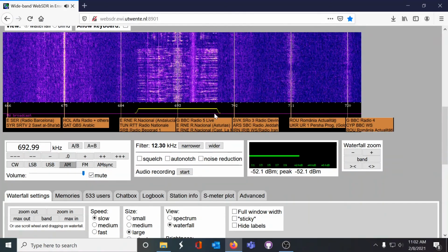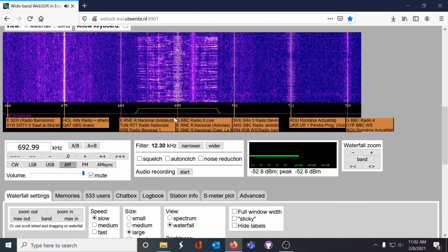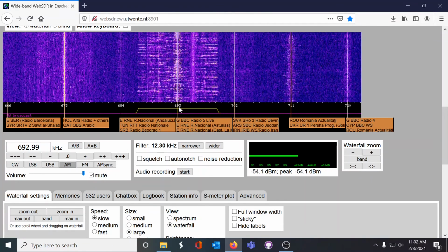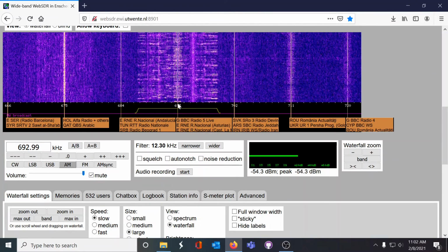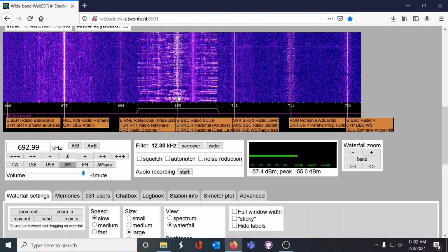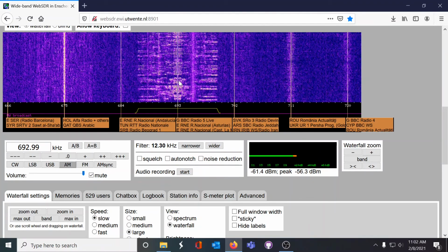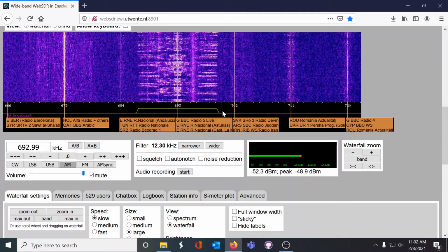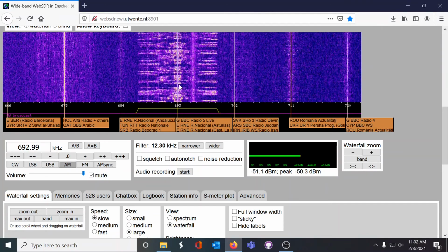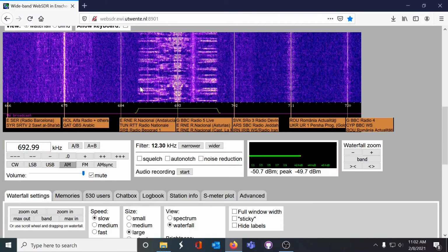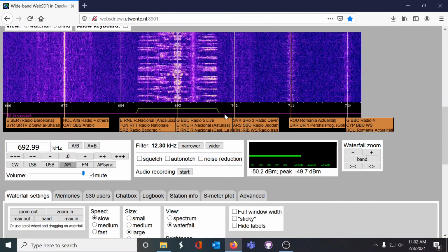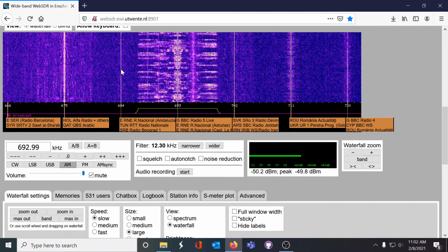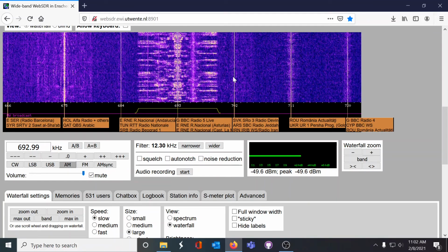If we go back to our software-defined radio, we are listening to the BBC Radio 5 at 693. Now that 693 kilohertz is the carrier frequency, right? That is the carrier, this bright band in the middle. The bandwidth of this particular station, you can see, is this frequency minus this frequency. And just so we can get our bearings here, this is the number 702, this is the number 684 kilohertz. The difference, which is here to here, is 18 kilohertz.